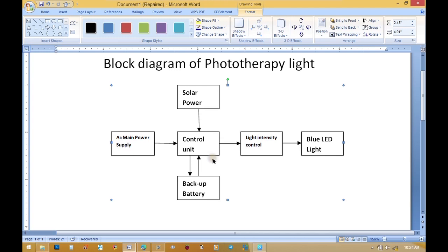And for the AC power supply, we step down the 220 volts with a step down transformer, step it down to 12 volts, rectify it, filter it, then we have a pure DC. We put an indicator light to show that there is light on the AC power source. Then from there we control the relay of the control unit using the AC power. So it is only the AC that will determine whether the relay will close or not. That is what happens on the block diagram.